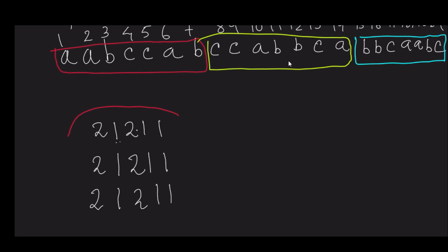So see, for this we can claim that here we are starting with, you can say, this is for A group. So this is related to A phase. So the first 2 conductors you will give to A, then the next one should be given to B, then the next 2 should be given to C, then again A, again B.